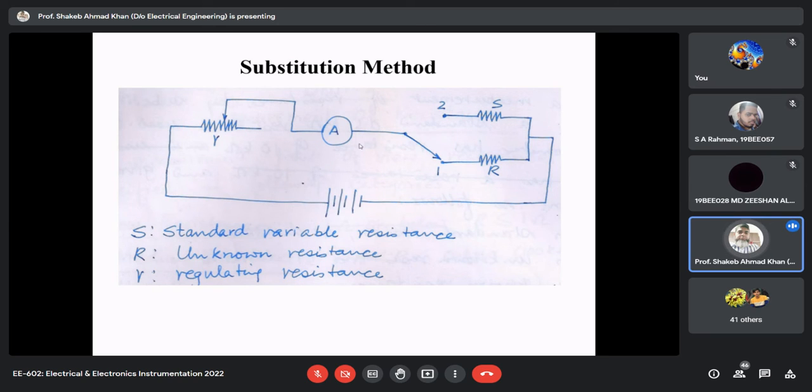If we are using more instruments, then there will be more error. And here instead of 2 instruments, we are using 1 instrument. So the instrument error will also get reduced. And then we are not having that issue that your voltmeter reading is not correct, your ammeter reading is not correct. In the previous case, that kind of issue will not be present at all here.